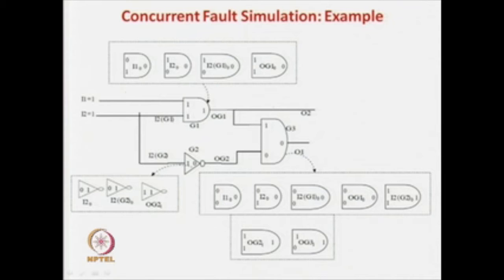Now, what we have in the normal case is 1 1 1 1 0. So, this is also 1 1 and this is a 0 and the answer here is a 0. Now, for this gate also there will be a lot of gates in the bubble which are actually affecting this one. So, now let us see how we can find out which are the faults affecting this one. You can see that this one depends on three values, the value here. So, these are the two values, I mean for this gate 1 0 is the normal case, and then we have to find the bubble list for this gate, that is, the faults which are actually affecting this gate.